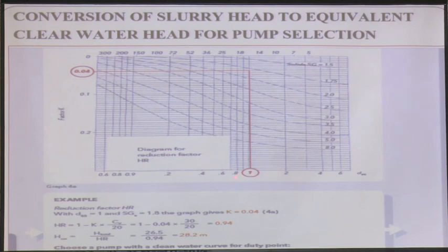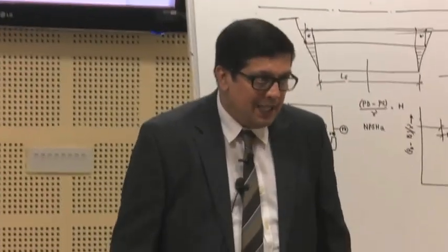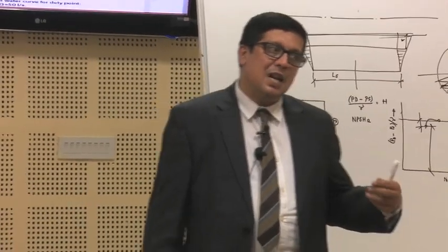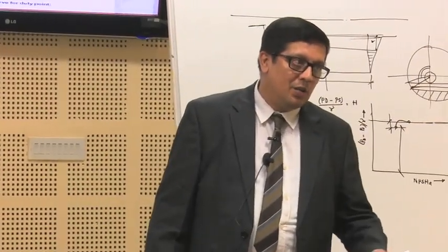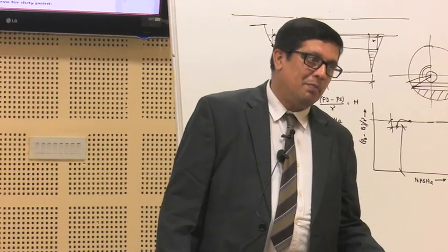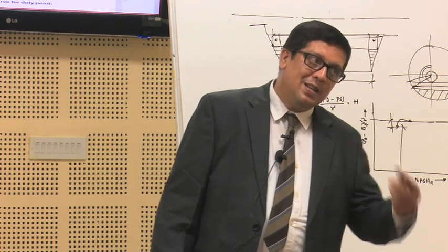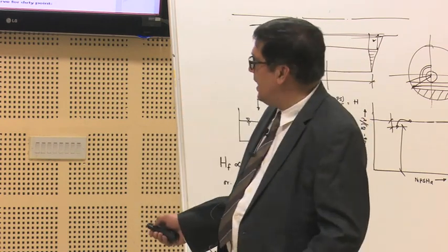So, in that methodology, what are the parameters that are influencing this? One is the particle size again, but this time it is D85. Can you just tell me why it is not D50? Anybody? Why is it D85? Because if it is D50, then it does not describe the particle size distribution totally, but if I know the D85, I know the bulk of the particle size distribution. The maximum part is known. So, all the influencing sizes are known, that is why it is D85, not D50.